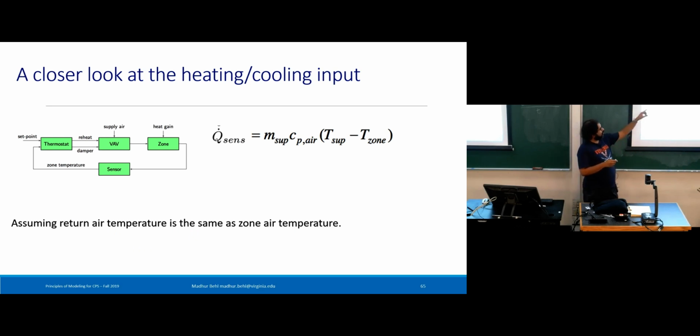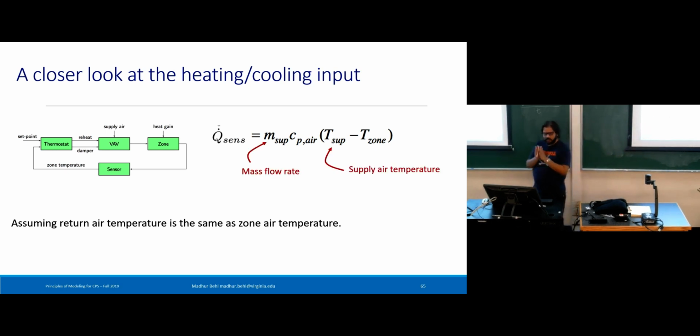So now you can associate the sensible gain and dissect it into a combination of two things you can individually control, which is the mass flow rate and the supply air temperature. These are things you can control, will go into the zone and, based on these disturbances, cancel them out, right? So mathematically, now you have seen what it means when I used to jokingly say that HVAC is canceling this heat that humans are generating. This is what is happening all the time.